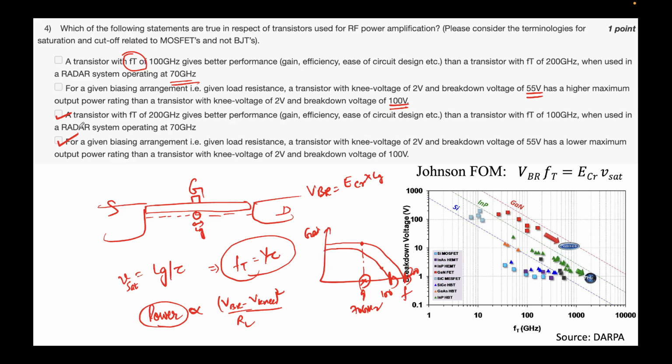And I'll again come to the difference, what makes it a power transistor or an RF transistor. There are some mechanisms like how much leakage you are getting and what the primary purpose is. Based on what the primary purpose is, that's how you design. For instance, the gate lengths that we talk about in the case of RF transistors are really small, and by really small I mean 100 nanometers or even smaller.